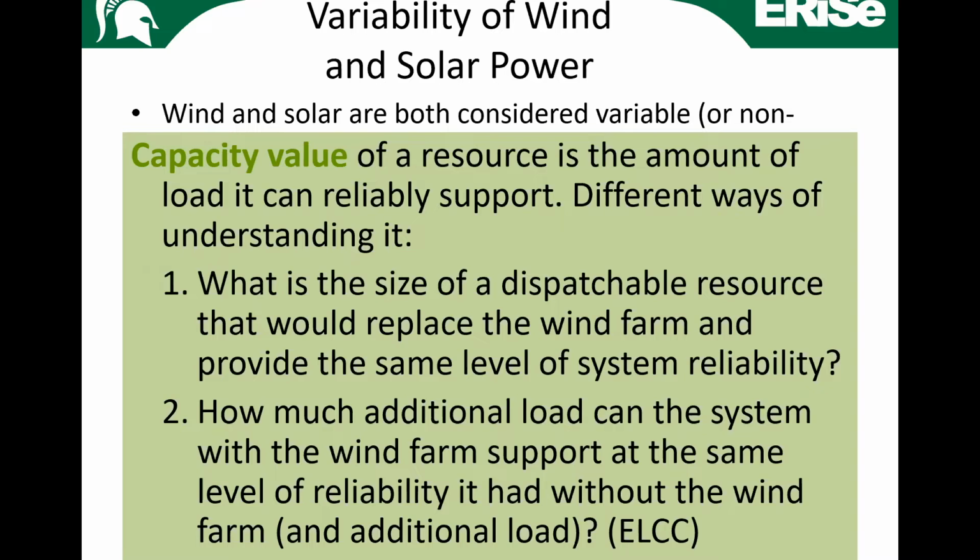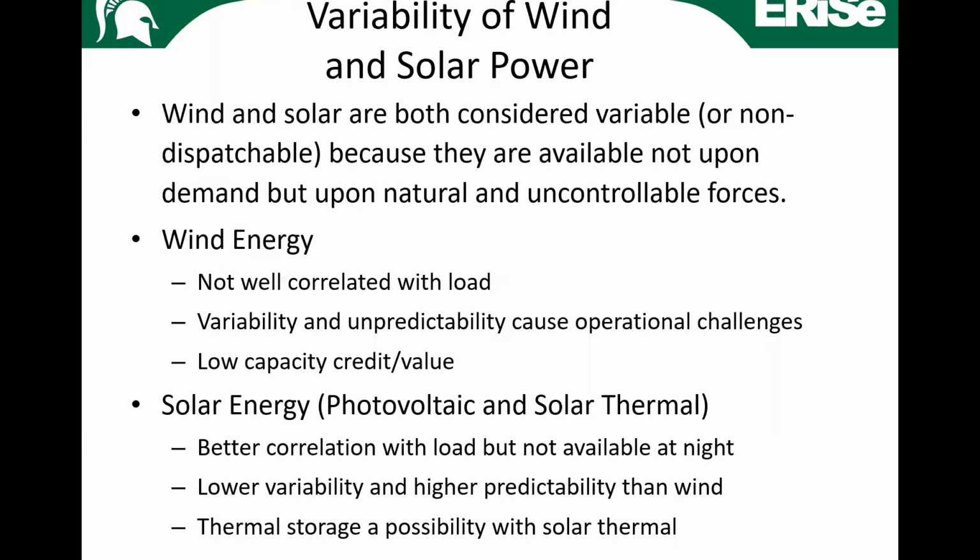How well interconnected is it with the grid? If it generates 100 megawatts consistently, a lot of the time, maybe not 100%, but a lot of the time, is the grid and the interconnection permitted to absorb the 100 megawatts entirely? Sometimes the answer is no, and you do what is known as spillage of wind. And so that should give you a sense of what capacity value is.